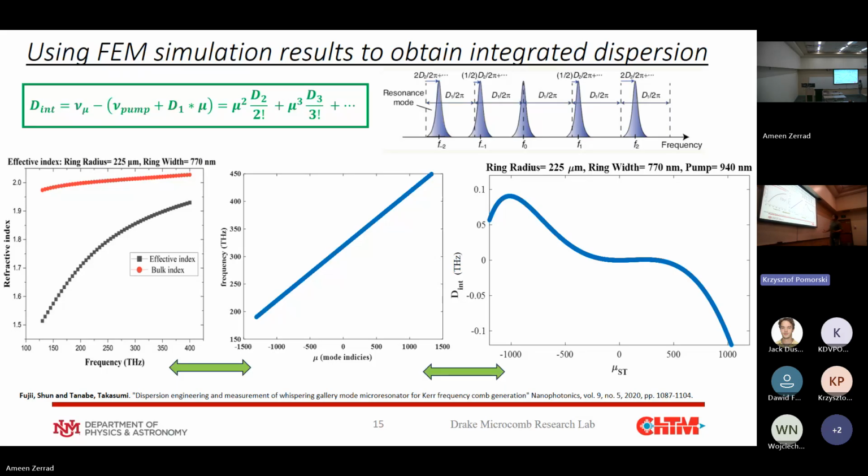And that's very important to have this curvy feature of integrated dispersion to support mixing in your microrings, or moreover, in our game here, to actually have spectral translation possible. So through your design of your integrated dispersion, you can meet your phase and frequency matching conditions to identify modes of spectral translation. And the way you tune this integrated dispersion, as I mentioned, is choice of material and choice of geometry. That's why we're varying the ring width and also the ring radius.